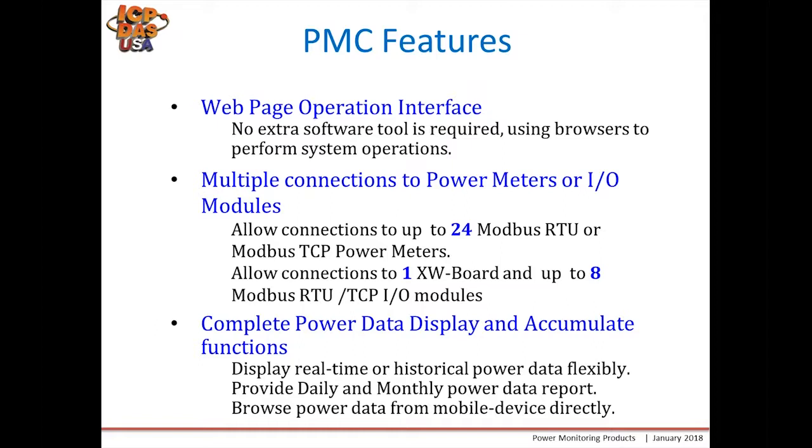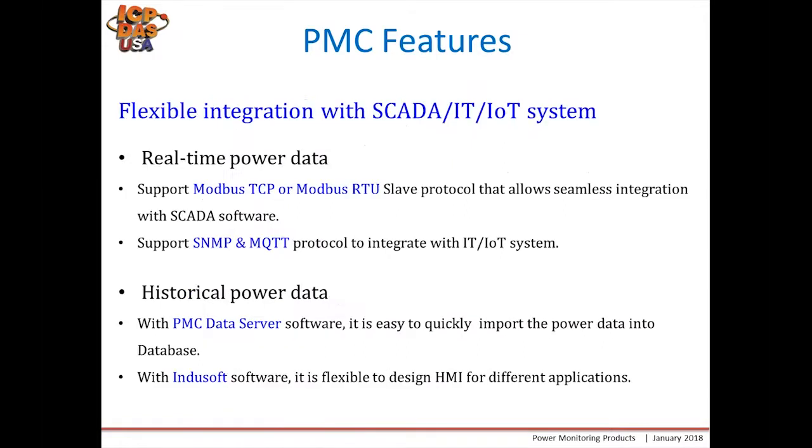Our power meter concentrators also communicate with SCADA systems and IoT systems with real-time power data, and they support Modbus TCP and Modbus RTU protocols for this. And some of our power meters support SNMP and MQTT protocols for communicating to IoT systems.